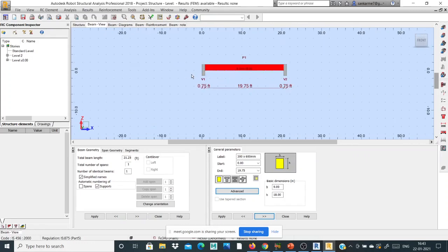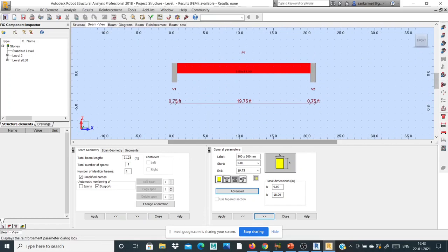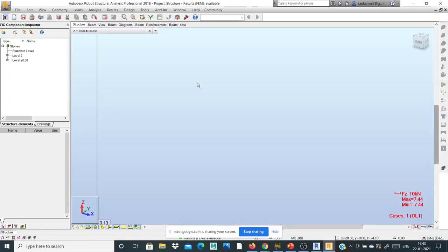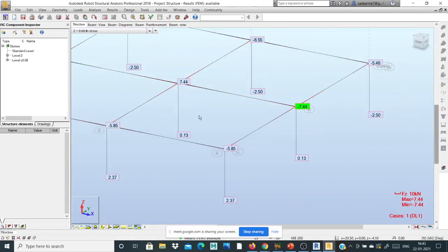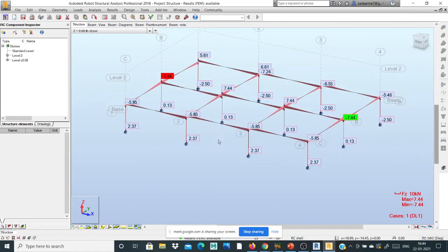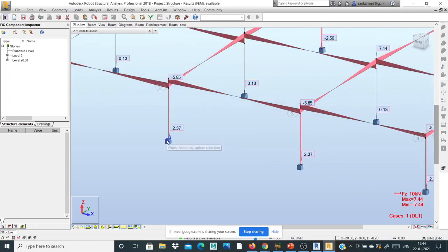Now understand, this is a simple procedure, so many things are there. I will tell about what is there in Robot Structure. You simply analyze and take the output file also in Robot Structure. I analyzed one beam, columns, etc. The column also follows the same procedure. I go to typical reinforcement, and the column reinforcement will be provided. Then I analyze the footing. First of all I analyze the beam, analyze the column, then finally analyze the footing also.